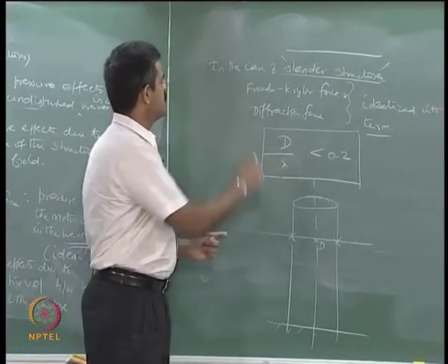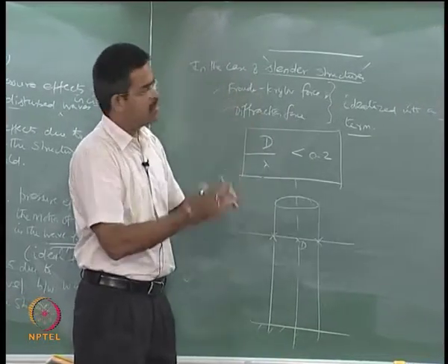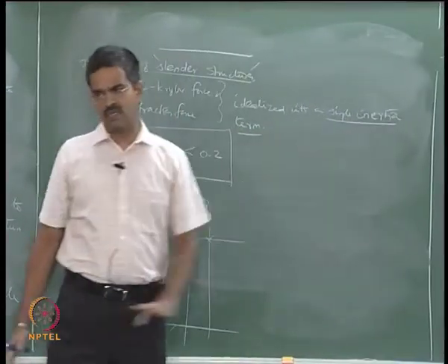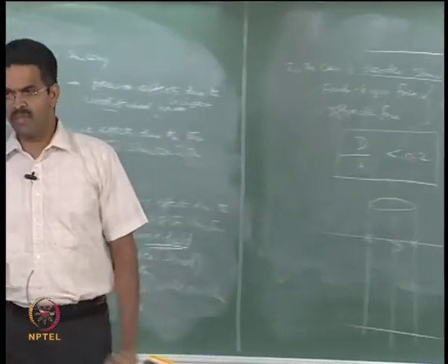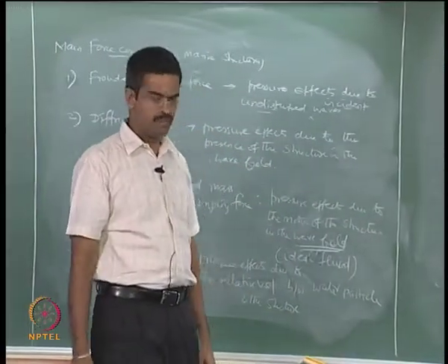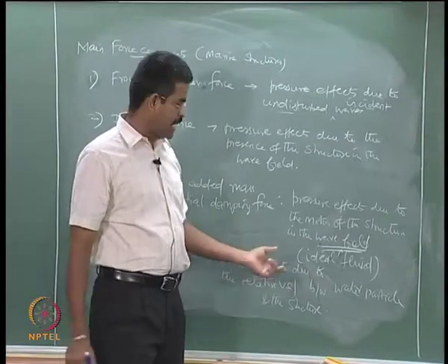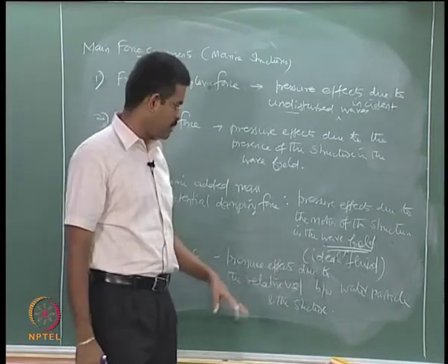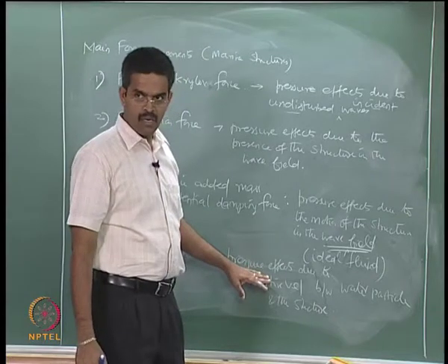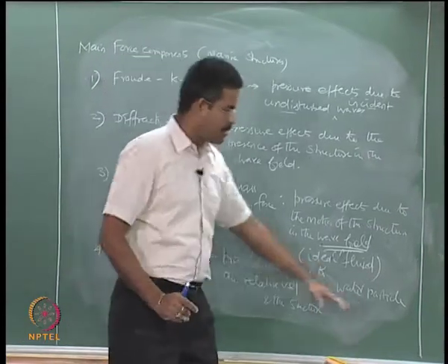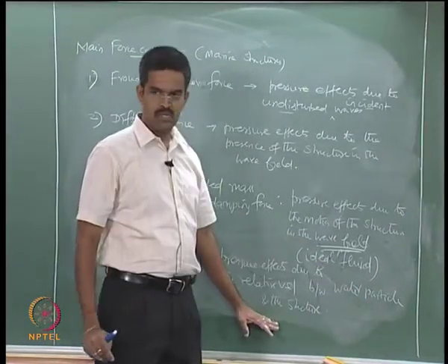In such case these two are idealized as a single inertia term. Now the question comes, how will I include the relative velocity term which is acting because of the pressure effects caused by the movement between the water particle and the structural member.